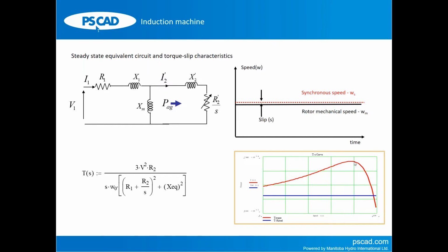And for steady operation, you have to make sure that the machine operates in this region. Because you're operating in this region, the operating slips are relatively small, right? This is your synchronous speed, this point, 1 per unit. Your operating speeds or operating slips are very small. The speed always is very close to 1 per unit of the synchronous speed. That is one characteristic of the machine.